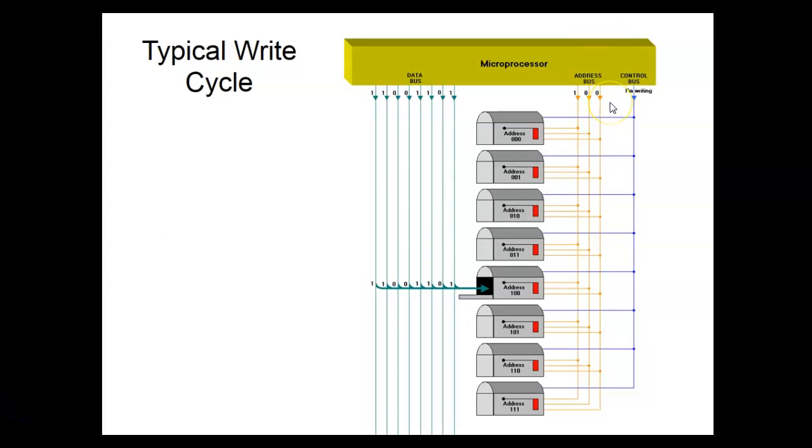So I got a 3-bit address bus, which means I can have 2 to the third things on my computer, which gives me 8 available addresses. So right now we're putting out this address right here, which is 4. It's a binary 4. The mailbox that has that same address, it opened up, right? You understand? All the other guys is what? Closed.